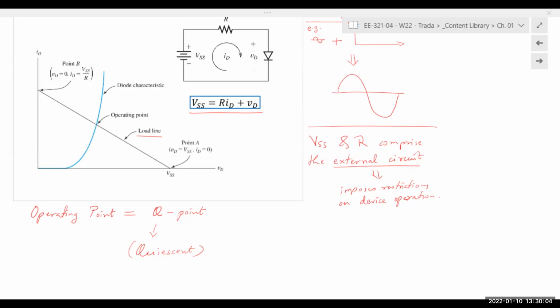So my negative signal moves along the load line, and the diode might turn off. Does that make sense? And so that's why the load line is of importance. We want to fix the operating point of the diode to be in the center region right here. Of course, it depends on the application I'm using the diode for.